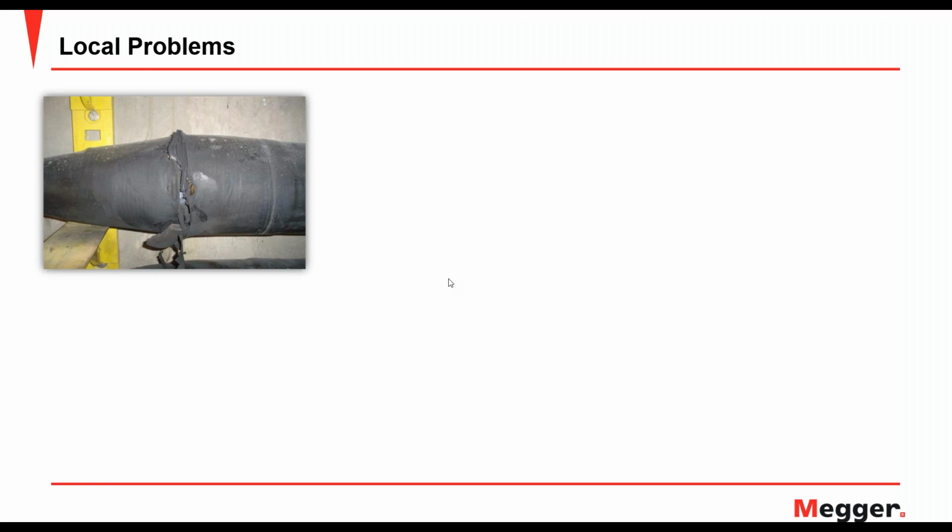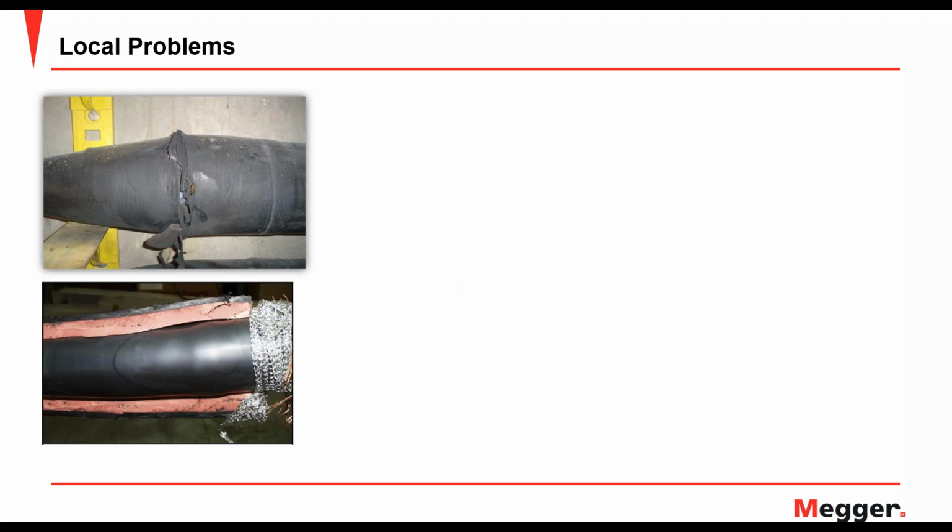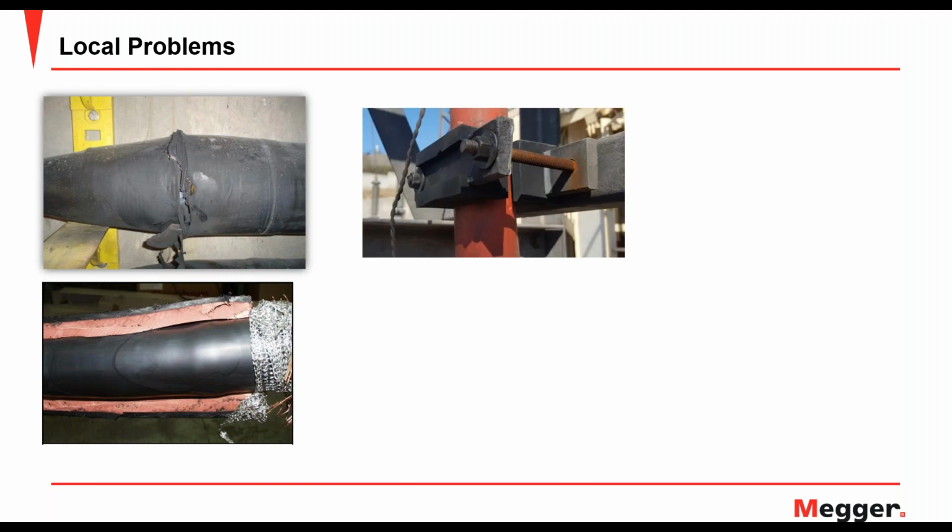Next, we do have a medium voltage cable here, where you can see that we have a heat shrink splice, and that splice wasn't heated all the way to be totally uniform or connected to the cable insulation there. And if we look, we can actually see resulting tracking, and you can see the cavity that's created there, partial discharge activity taking place, and you can see that tracking on the cable insulation itself.